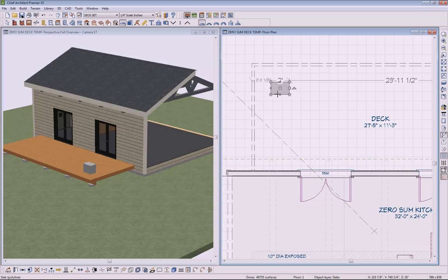So with that selected, I'm going to go down here at the bottom and click copy and paste in place. So I get another exact replication of that, and it's pasted in place. And I'm going to grab the corner of this, hit the C key on the keyboard and pull that out to make a concentric copy of that, basically expanding the size of it concentrically.